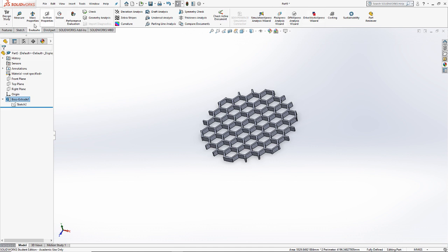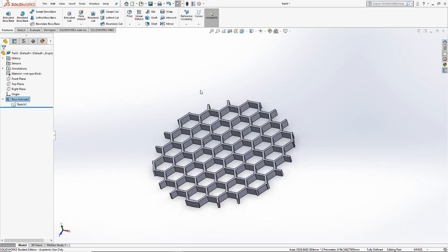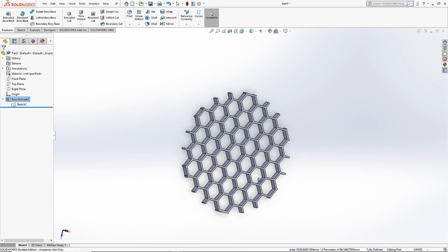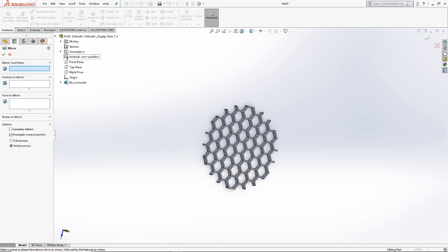So, we've talked about fillets, we've talked about patterns, we've talked about reference geometry. The last real tool you have to be able to use here is a type of pattern called mirror. It's so important it has its own dedicated button, but either one is just fine. If you create something in SolidWorks that has symmetry and you want to just pattern it, you can use a pattern like a linear pattern, or in the event that you have mirror symmetry, you can generate a mirror.